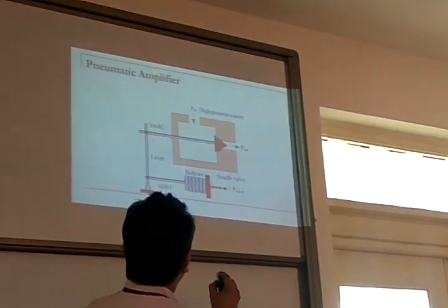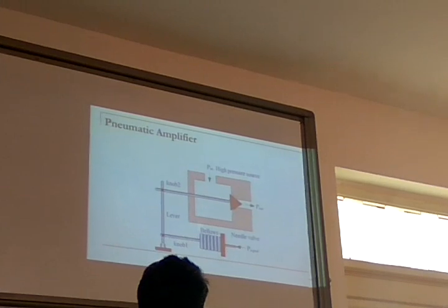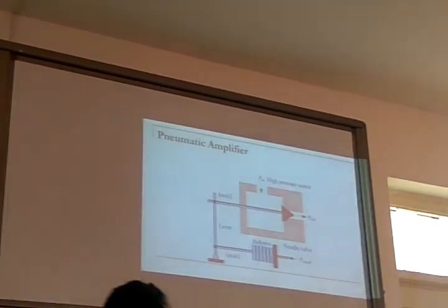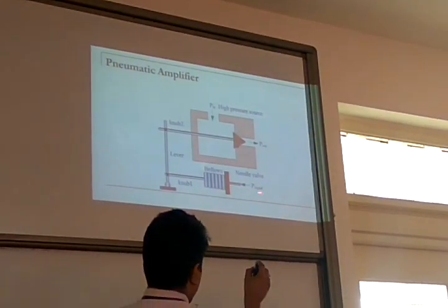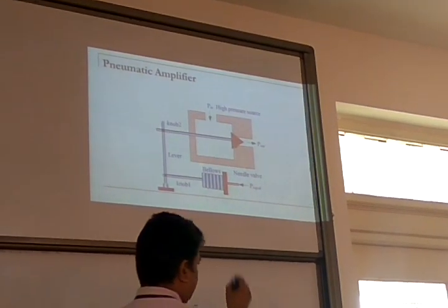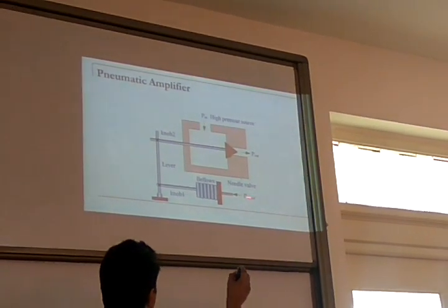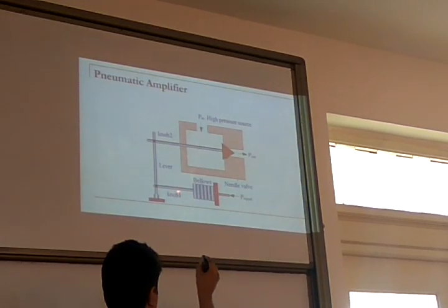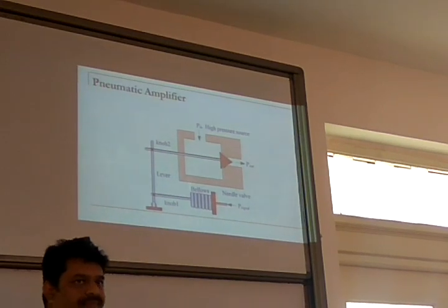Okay, let me try. This is a valve, let's say a pneumatic valve operated by pressure. Here there is a small pressure that I can give. There is a bellows. Bellows means a balloon structure. I already explained what is bellows. So here you apply pressure to bellows. Bellows will expand and push this knob 1 towards left.